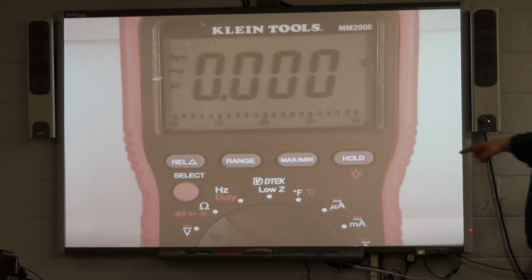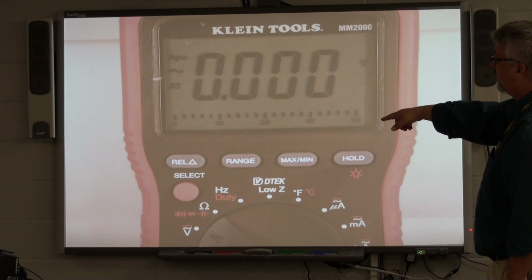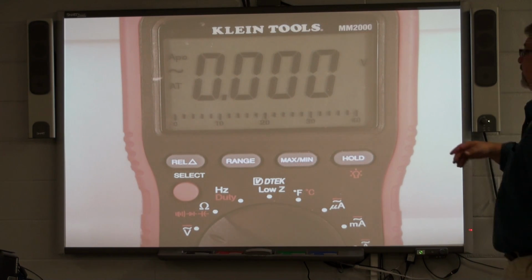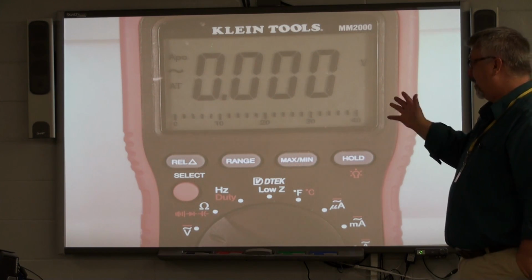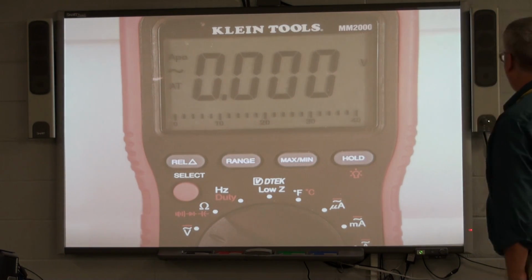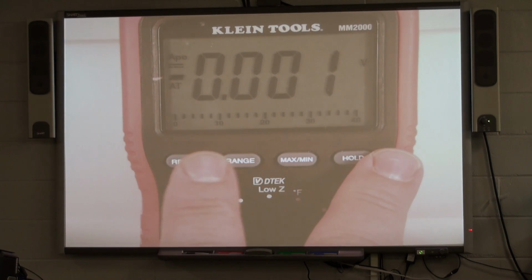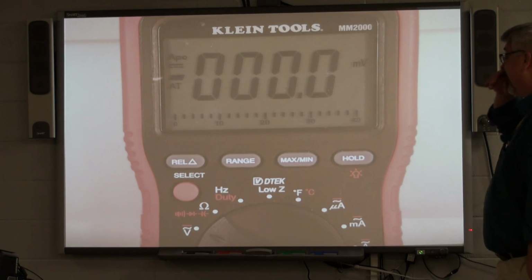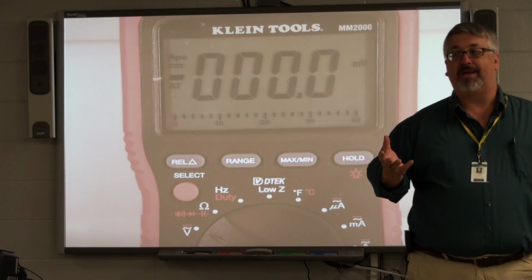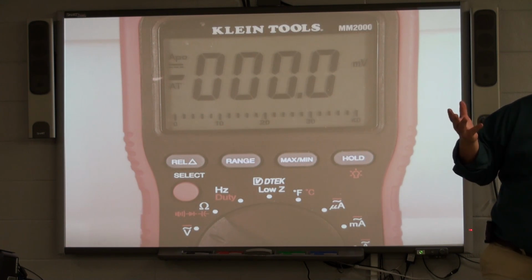Volts is expressed with the wavy line for AC as white, the orange or red as some of you call it. I'm not sure which of us is colorblind, but I call that orange. The straight line is in orange, so to change that wavy line, which represents AC, I'm going to have to press the orange button, and it'll change to DC. So again, getting our meters to a particular setting can be a little challenging.